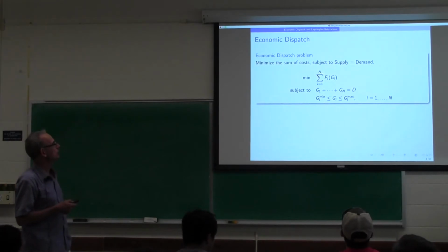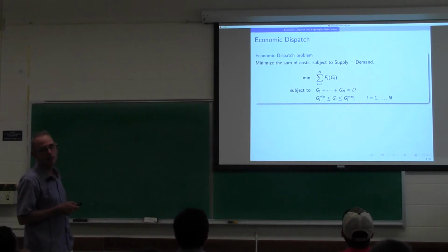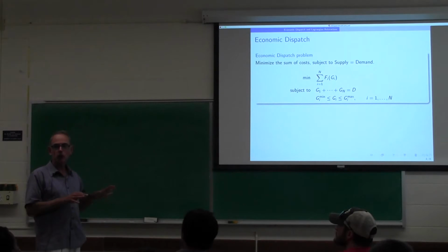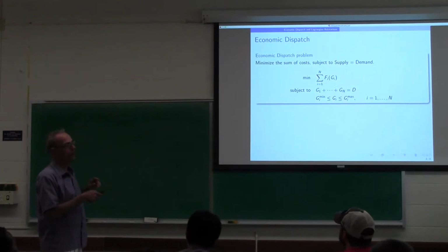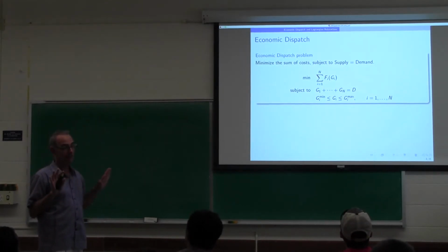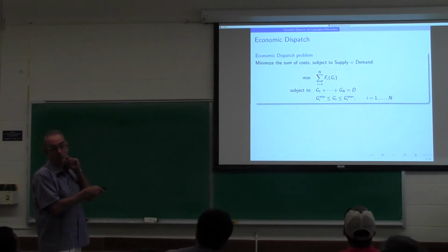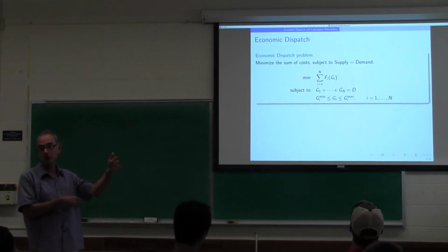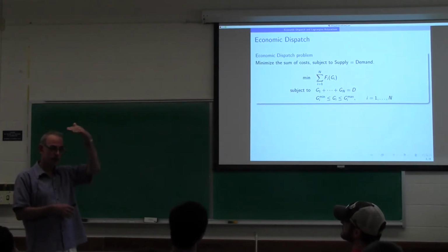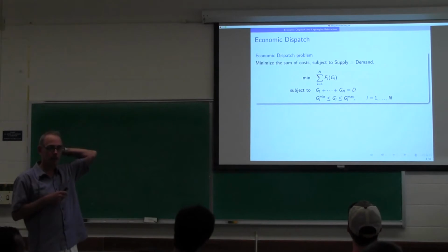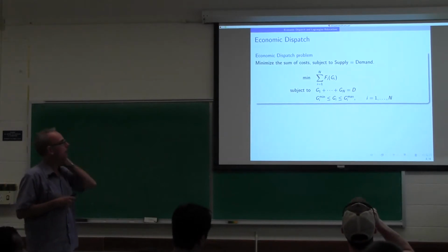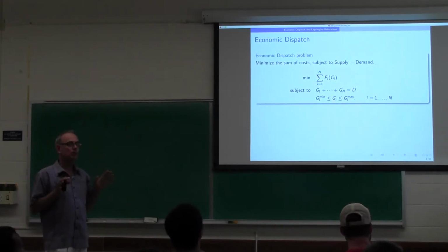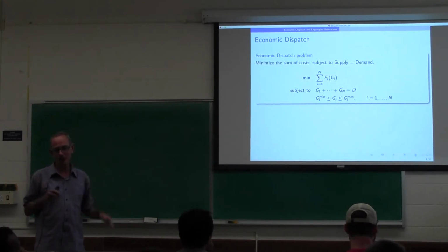So basically we've got different generators that have lower limits and upper limits. Now remember, we've solved the unit commitment problem, so these n generators all have to be operating. There's a hard constraint below, which is not 0. We assume we've already solved the unit commitment problem, and now we're deciding what level each generator should be operating at. That unit commitment problem is a whole other course. We won't get into that.